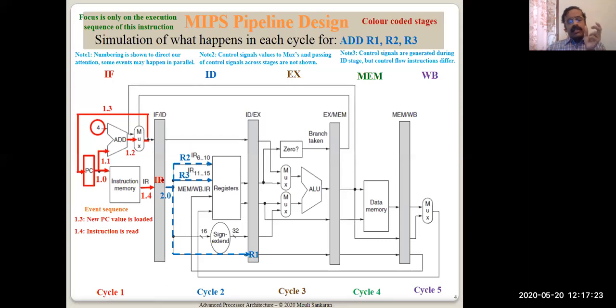It says the opcode, what the operand registers are, whether it is R2 or R3 or R4, and if it has a destination register, its number, whether it is 5 or 6 or 7. In our case, the destination register is 1, one operand is 2, and this is 3. So these are all the actual registers to be accessed. It is showing that I want to access the operands R2 and R3 from the register set.